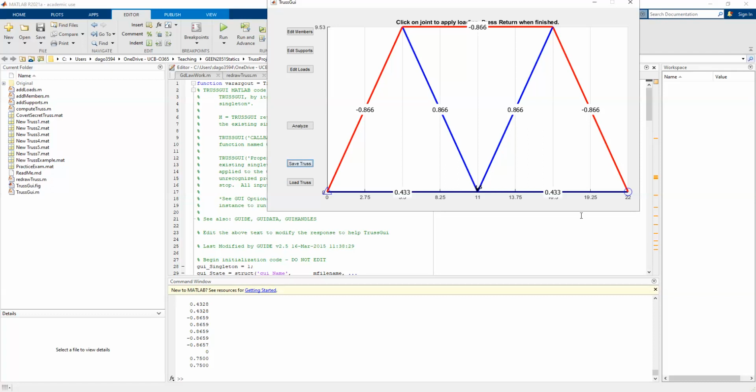So having this MATLAB, we would go into Excel and start doing these. These are just the forces. So if we had a load of minus 1.5 kilonewtons or minus 1.5 kips, so 1,500 pounds, this is how many kips we would have. That would be 866 pounds. But what we care about is not necessarily the forces. That's the first step. What we care about are the stresses. So we'll take the forces we get in MATLAB, and then we'll actually look at how to take these forces and do a stress analysis using some Excel. So that'll be the next video.